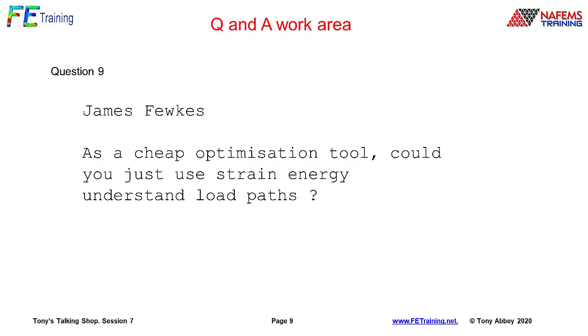On the course, I show a fully stressed design approach where I do exactly that. A cheap optimization tool, all I've got is a macro which just goes through and says, well, if you have stress below a certain level, remove that material, and then at that stress removal level, just iterate till you get a stable load path. That's your first step, and then just keep doing that as you remove higher and higher stress levels. Stress isn't a good thing to use, because if we've got indeterminate structures, we get into trouble with that. Strain energy or compliance would be a better thing to use there. So yes, if you can set yourself up a macro to drive down there to remove material, then that's a good way to do it.